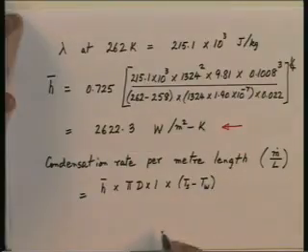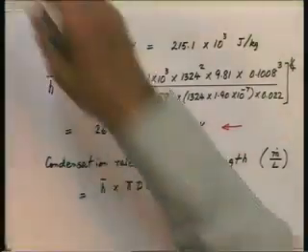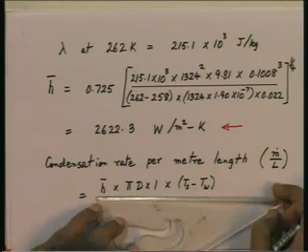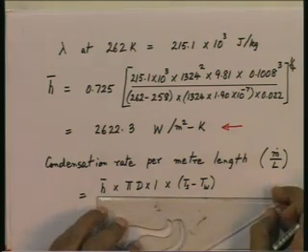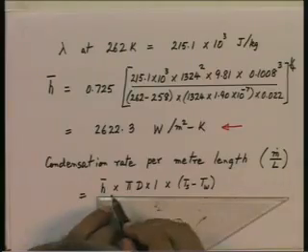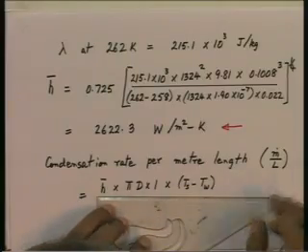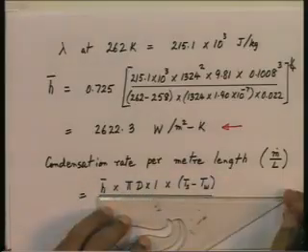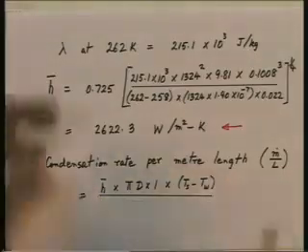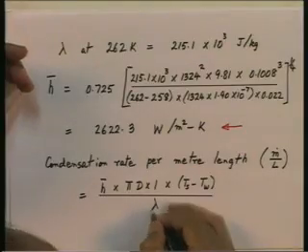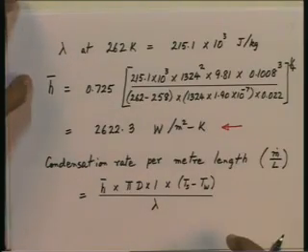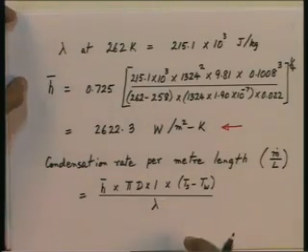This is not heat flux, sorry, it is the rate at which heat is flowing, Q. If you divide this by lambda, the latent heat, then we will get the condensation rate for 1 meter length, because we are taking L equal to 1.